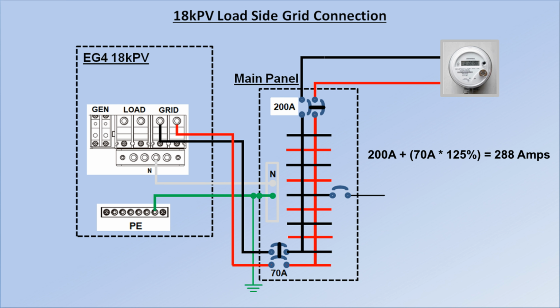In this case, the bus bars would have to be rated for 288 amps, which they obviously wouldn't be in the average 200 amp service. So this is a no-go. But wait, there's more.